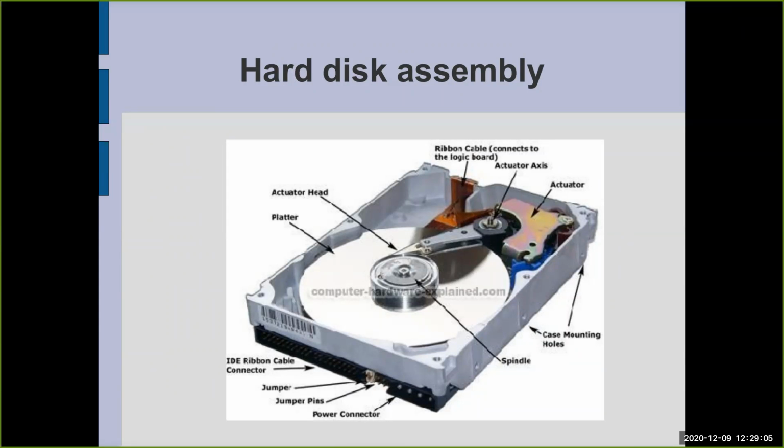So first, when you power off your hard drive, the head is parked, so it is moved outside the platter surface. Automatically, when the hard drive is powered off, this arm is moved to this place, the parking.